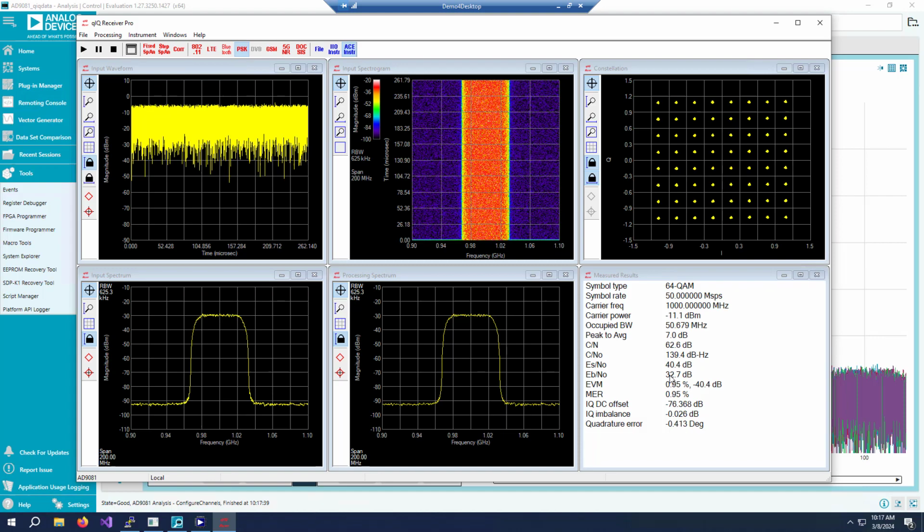in the system. Then we go through a whole demod and we get these final symbols and we do EVM measurements and things like that. So here we go. Here's EVM, and EVM expressed as percent, or some people like EVM as a negative dB type of number, so that's in there.